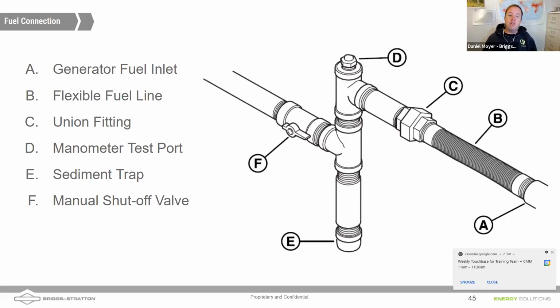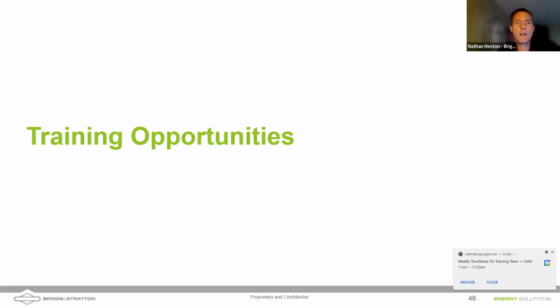I will just say this: although you're going to have maybe a certain number of run feet of pipe, every one of those valves, every one of those T's, every one of those elbows is introducing additional resistance to the flow of the gas. So it should be accounted for when you're sizing your gas lines. I know there's a move to use corrugated stainless steel tubing in a lot of these connections, and buried connections as well. Well, that's a different amount of resistance in the flow rate of your gas. So keep that in mind and utilize our tools for sizing your lines.